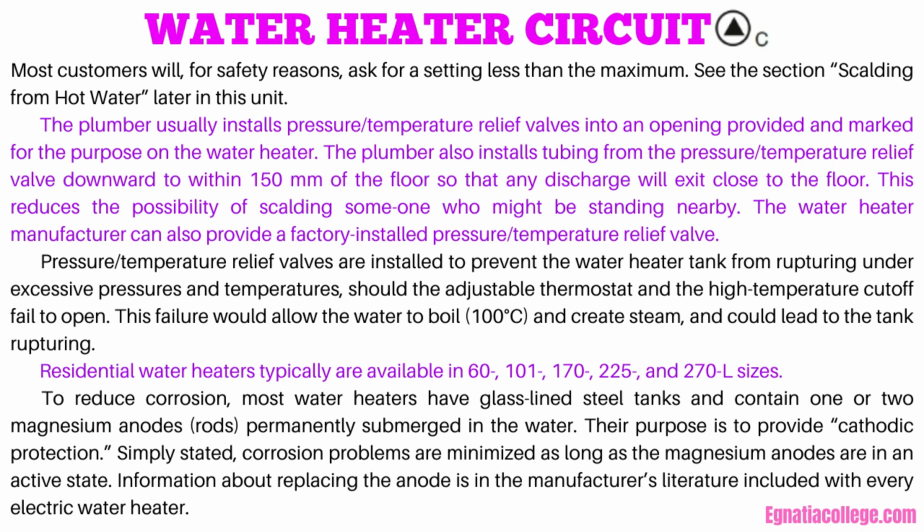The water heater manufacturer can also provide a factory-installed pressure-temperature relief valve. Pressure-temperature relief valves are installed to prevent the water heater tank from rupturing under excessive pressures and temperatures, should the adjustable thermostat and the high-temperature cutoff fail to open. This failure would allow the water to boil, 100 degrees Celsius, and create steam, and could lead to the tank rupturing. Residential water heaters typically are available in 60, 101, 170, 225, and 270 L sizes.